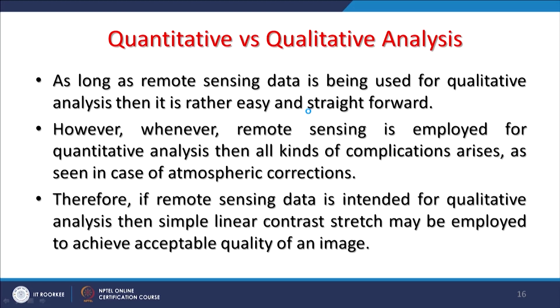And therefore, if remote sensing data is intended only for qualitative analysis, then the brute force method or linear contrast stretch method can be employed, and it will give you a better quality image, which is sufficient for the purpose for which we are using the satellite images. So, in that way it becomes much easier.